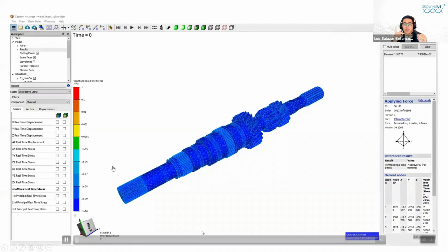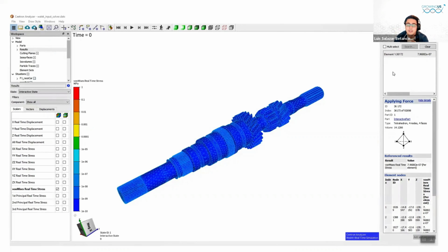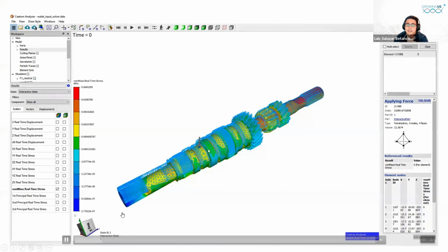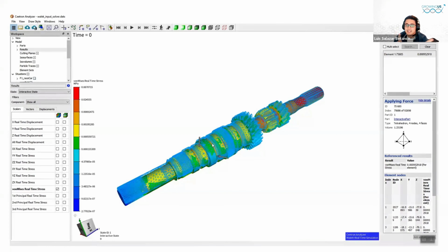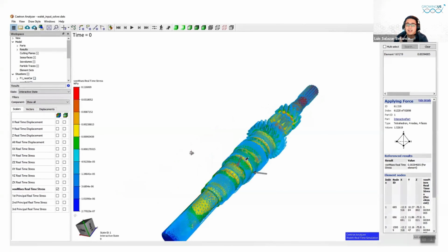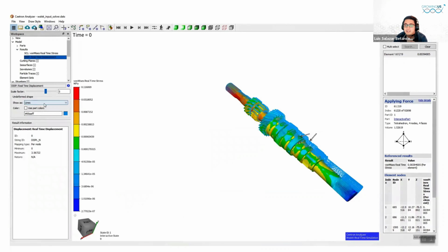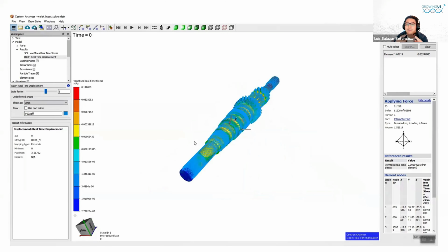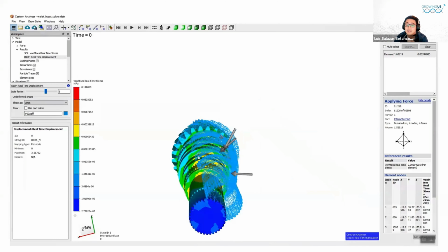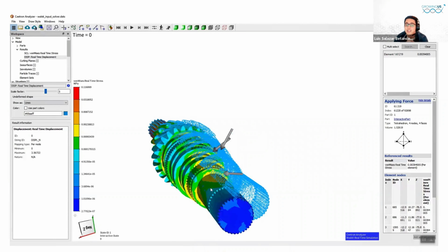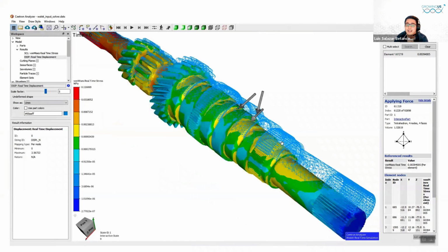So this will recall what we have been doing in the hackathon. I will use the same model now to show another example, which is to be interactive. In the same way, I have imported the CAD model, and now I can add force. What I'm doing here also is overlaying the original geometry. And of course, I am amplifying the deformation a little bit, but we can see interactively how this part, after fabrication and while operating, will be deformed from its original CAD design.